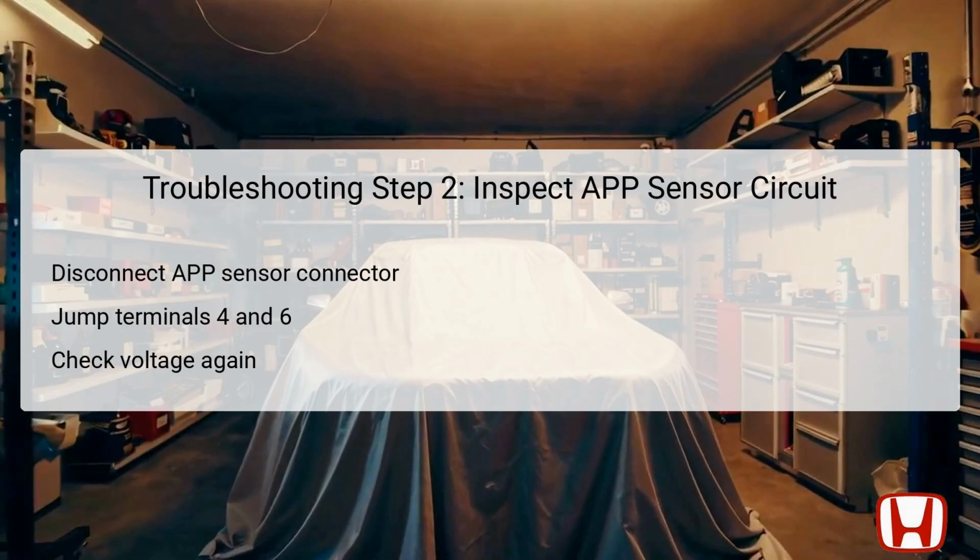Next, use a jumper wire to bridge terminals 4 and 6 of the sensor connector. This creates a controlled condition to test whether the APP sensor is the source of the issue. After jumping the terminals, turn the vehicle's ignition back to the on mode. Again, check the HDS for the APP sensor A voltage. This allows you to confirm whether the signal output is operating correctly.